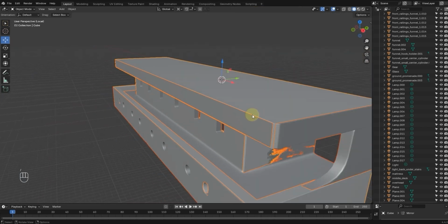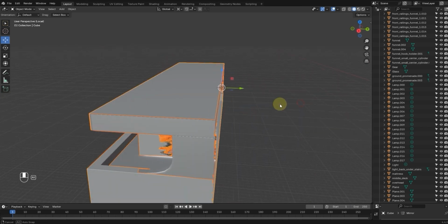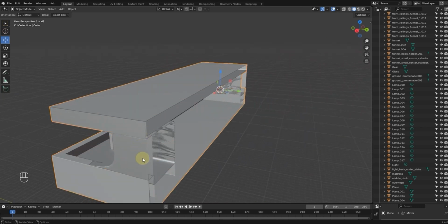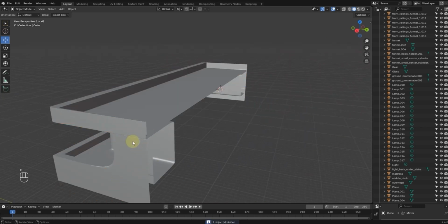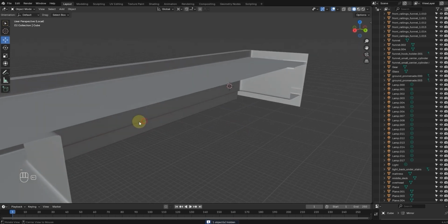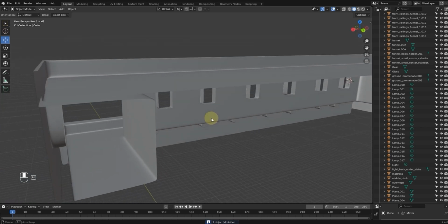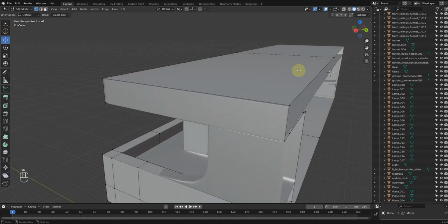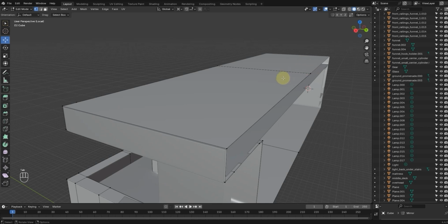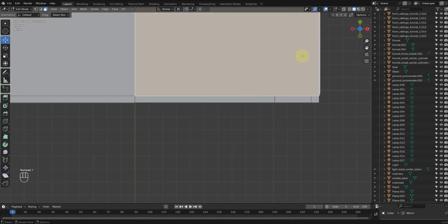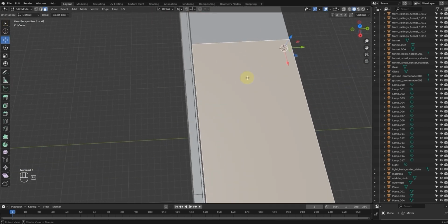Now I noticed that there's a missing part that I haven't actually completed. That's the open balcony at the top there. So I need to come back here and sort of work on the size, the layer, using insert and then resizing the face and bringing it down, extrude it down. So I'm going to go to the top and then use insert.